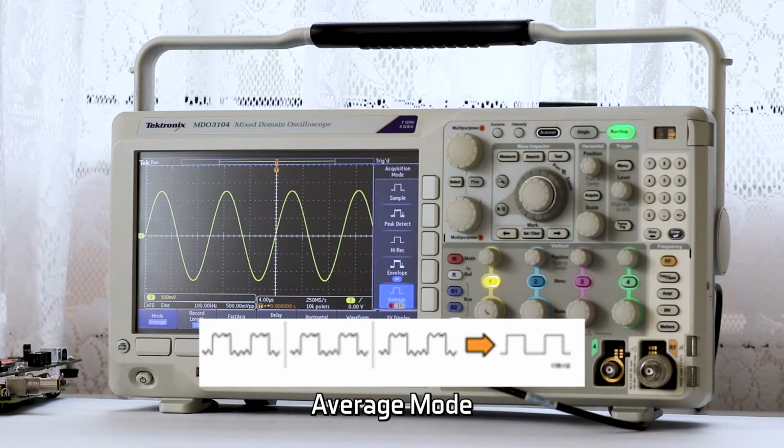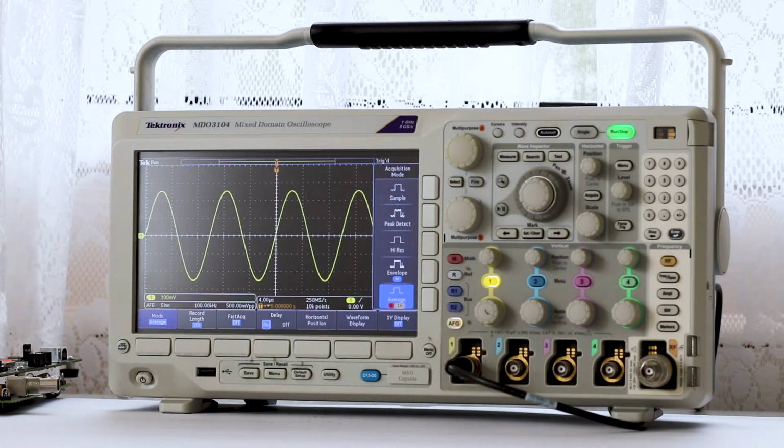Average mode is highly effective in reducing noise. The way it works is that successive acquisitions that are averaged are periodic and coincide, so these signals reinforce one another. Noise, however, is random, so it cancels out rather than reinforcing. To illustrate how waveform averaging can clean up a noisy signal, press AFG so the sine wave is displayed.